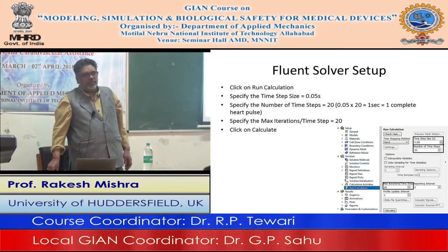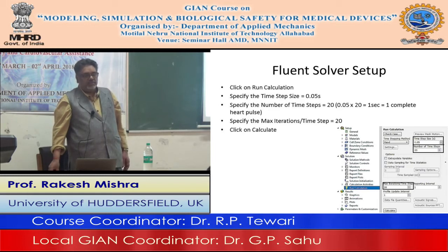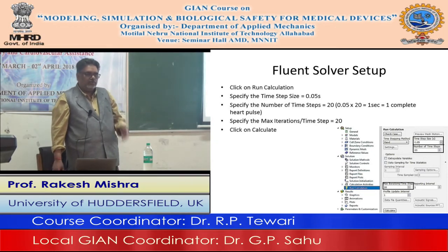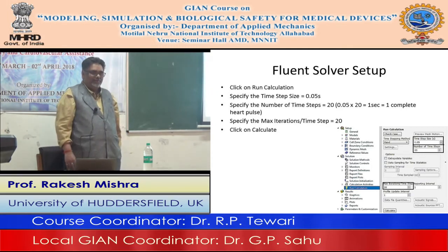Yes, whatever best you can have. If you have faster computers, try to have it. Your aim is to have the flow phenomena rightly mapped. So there are some guidelines on that. If you look at some references on how the time step size is fixed for LES, for example, large eddy simulation, they define a structured process to calculate the time step and the mesh size. Because you're simulating the large eddies, and for the small eddies you're using physical models. So there are some instructions for that. In this particular case, what I've taken is okay.